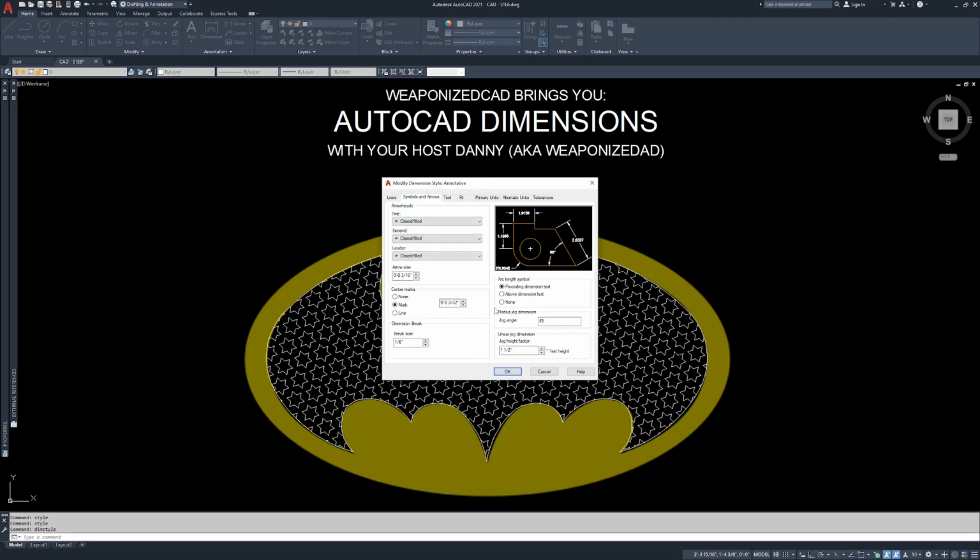Symbols and arrows, we're also not going to touch. Text, we want the text style to be annotative because that's the one that we just set. We told it to be annotative text. We told it to be 1/8 of an inch. I know we haven't covered annotation yet. Annotative scaling, all that stuff that's coming with the layouts, and it's going to continue from there. So I know we're kind of jumping around a little bit, but just stick with me. This is going to stick in your head, and you're going to remember it when we get to that point and go, oh, that's what he was talking about.